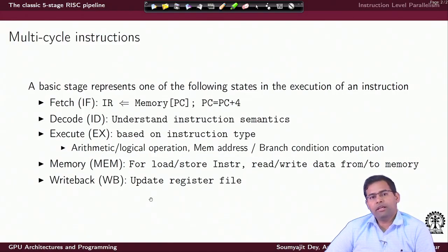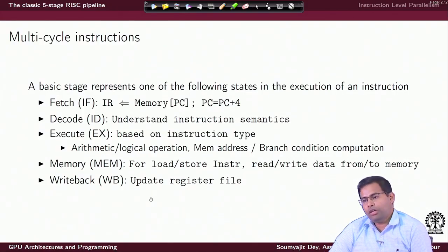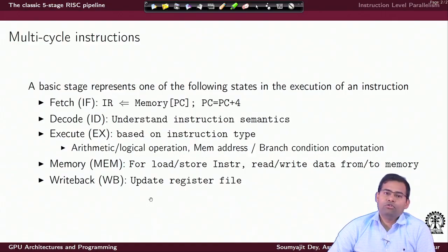For example, if I take the example of a load instruction, suppose I am loading the value from some memory location X to some register R1. The access of memory location X and fetching the data from that location to some specific register called the memory data register should happen in the mem stage. Then writing this data from the memory data register to the specific register R1 in the register file, this update of the register file shall happen in the write back stage.